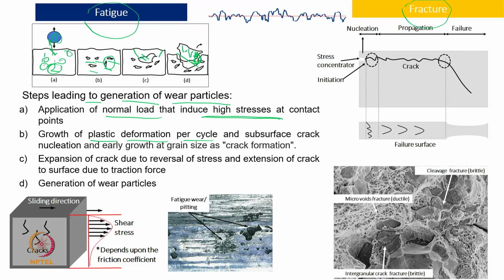However, if plastic deformation continues and does not come back to elastic deformation, then the running-in period will be zero, and we will get some sort of continuous deformation. That will also create some sort of subsurface crack. Maybe if there is some very nanometer-level discontinuity, that will increase in